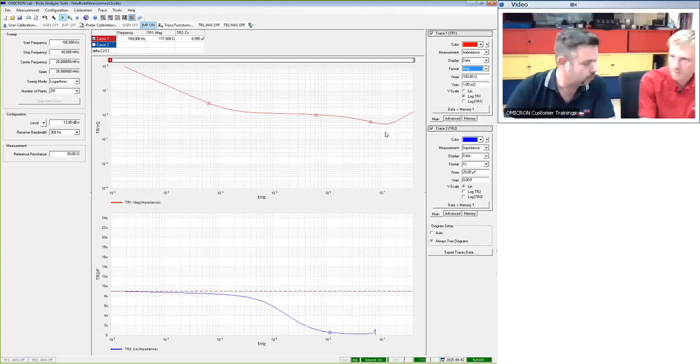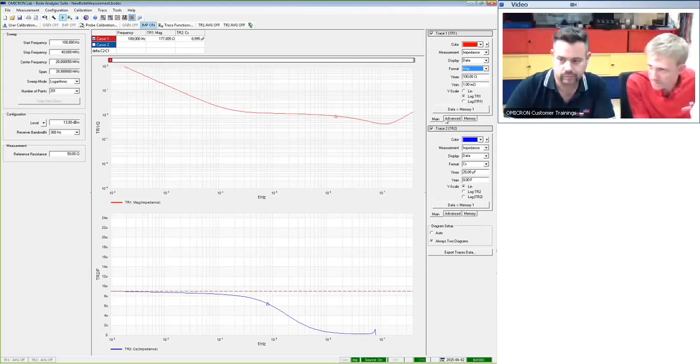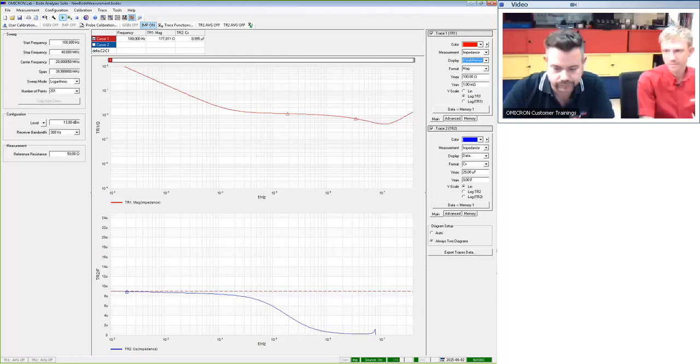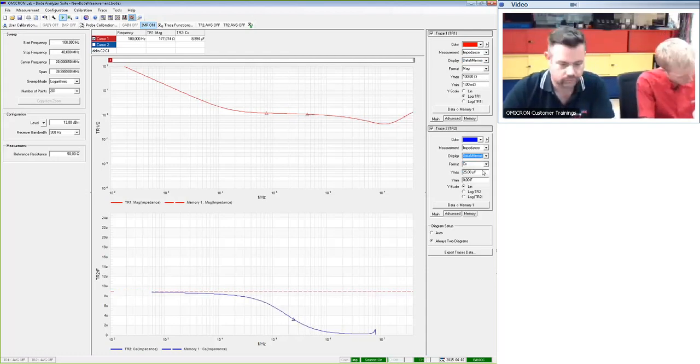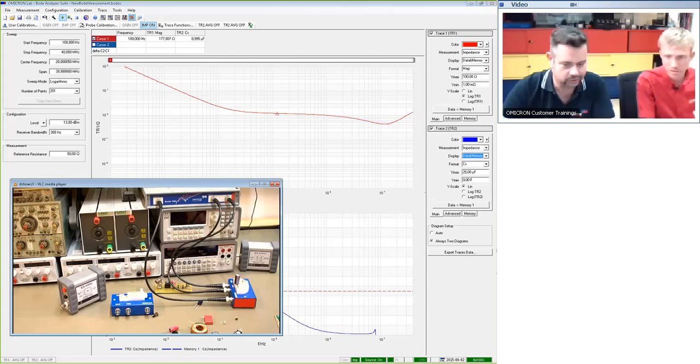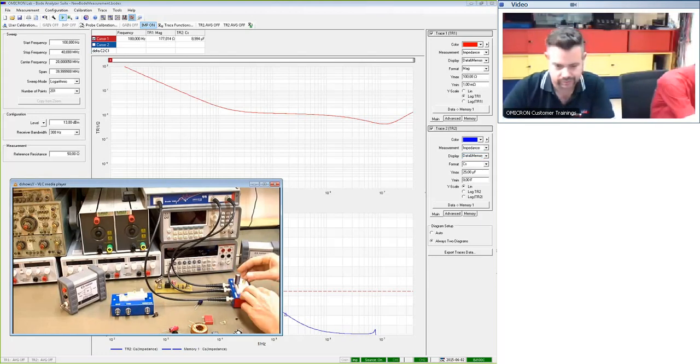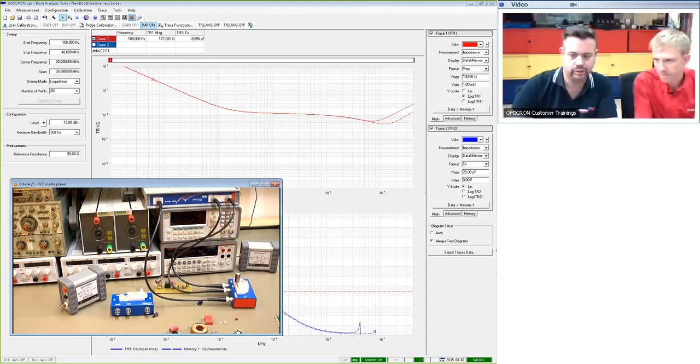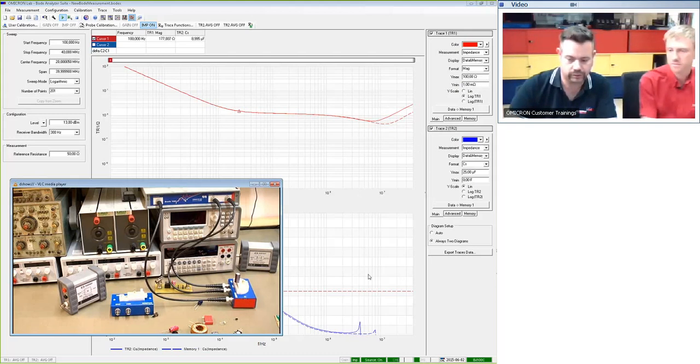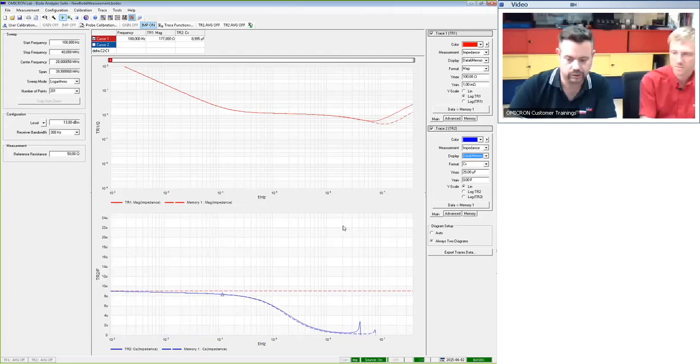And now please pull out the capacitor a little bit from the fixture. Can you select data and memory? Yes, I will do so. See the difference, data and memory. So I'm pulling out the capacitor from the fixture now. I will put the camera on. So, now I just pull it out by approximately 5 millimeters. And you can immediately see the change at the upper frequency. The inductance has moved. In fact, the resonance frequency has moved. We can see this down here.